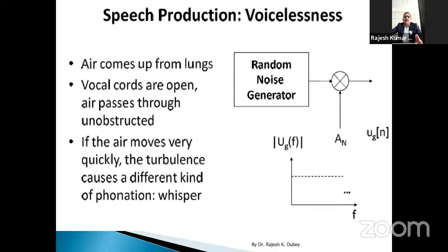Other important part is unvoiced production. I said speech now has two parts. The voiced production, the voicing part, is because of vocal cord vibration that introduces the fundamental frequency and formant frequencies. From a DSP engineer's point of view, we think like that. When we are speaking, in the speech production model, the lungs and vocal cord introduce frequencies into whatever air is pushed from the lungs.